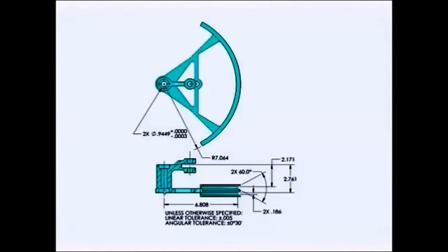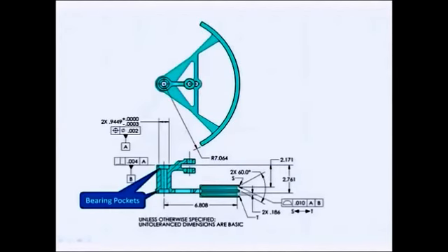Also, the bearing pockets were machined in one setup, and then they would refixture the part to machine the radius in another setup. So, oftentimes, the center of the radius was not right at the center of the bearing pocket. The solution is to identify these bearing pockets as your primary datum feature. As you can see here, I'm calling it datum feature A, 2X, so the 2 pockets establish a common axis that the pulley can then pivot around.